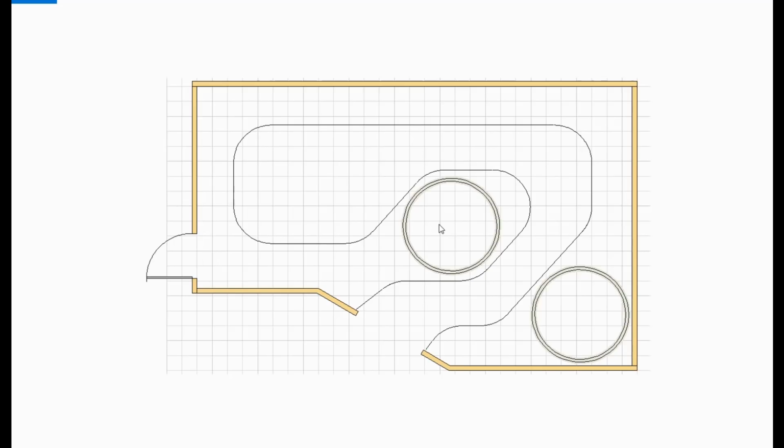Now, the specifications that I was given were for long diesel hauled trains over a double track main line. So I wanted to use a decent sized curve. Originally I started off using a 3-foot minimum radius on the inside track, but later ended up shaving it to 33 inches because it wasn't possible to get two of the 36-inch double track radius curves side by side in this end of the room.